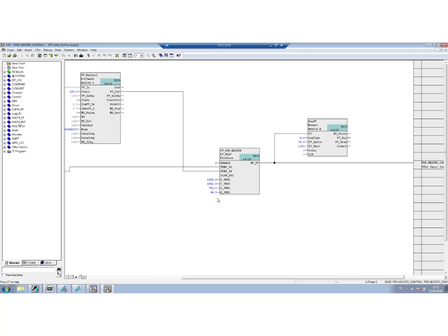And you can set the different parameters to compute this feed forward gain based on the product density, the product specific heat, the fuel density, and the fuel heating value. And this is calculating the feed forward, the pre-computation of what you should use as a fuel flow, right? And you can enable and disable the feed forward.